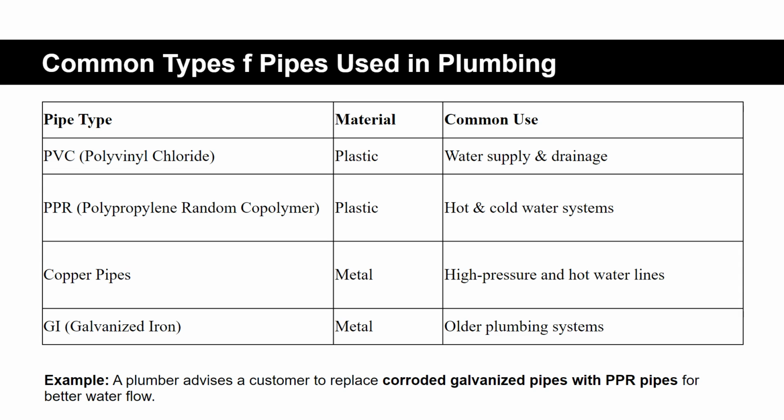Corrective maintenance. This happens after a fault is noticed. Maybe a small leak, a clogged pipe, a valve not opening right. It's fixing what's wrong before it gets worse. Emergency maintenance. This is firefighting, a burst pipe, a flooded room, a total pressure failure. It requires fast thinking, fast action, and solid skills. And it's where reputations are made or destroyed.